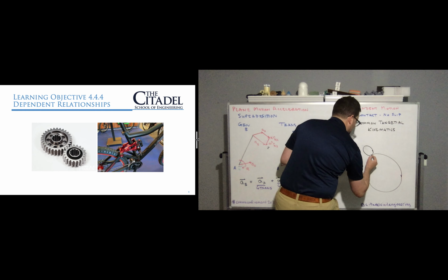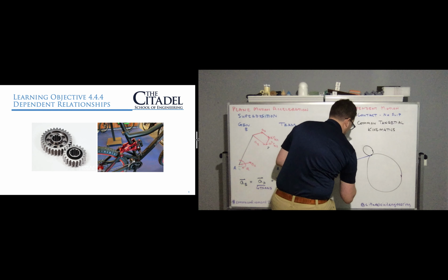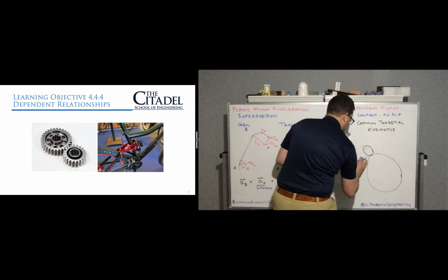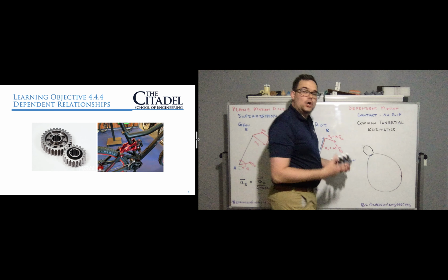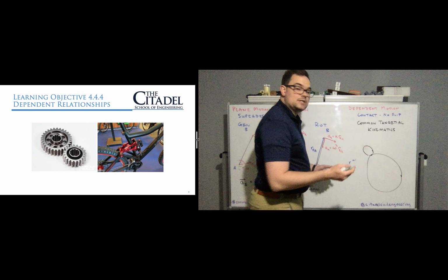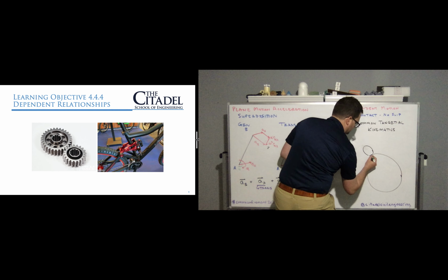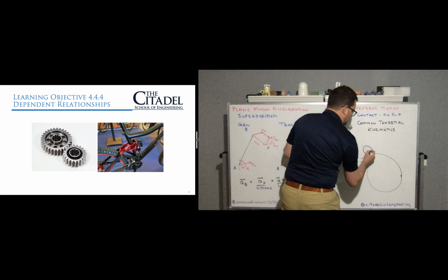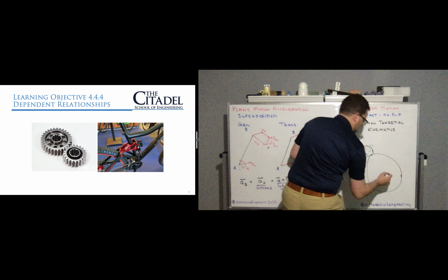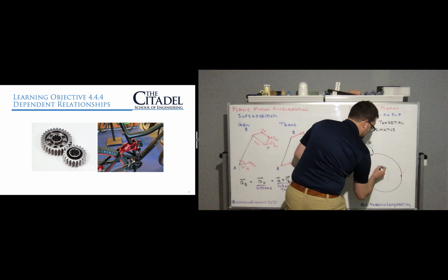So we'd have a tangential direction that looks something like this, right? In the tangential direction. And in the case of velocity, all of the velocity was in common. That's because all of the velocity is tangential to those 2 shapes. So we'd have our velocity there, common between the 2. Now each is going to have its own omega, or angular velocity, about the center.